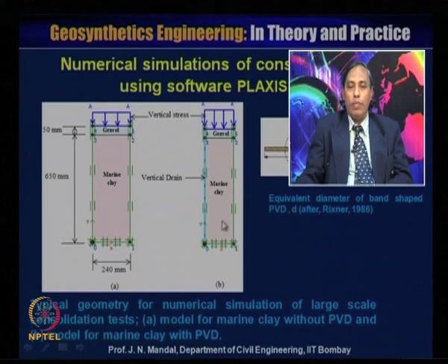You have provided the PVD here, and this size is about 240 millimeter, this is 650 millimeter, and there is a gravel of about 50 millimeter, and then you are applying the vertical stress. And this is the vertical drain here.